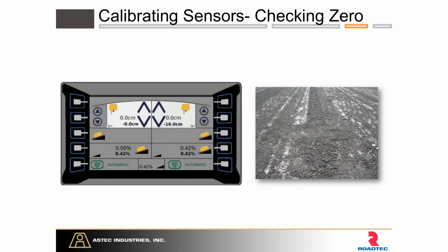So at the beginning of the day, we lower the machine down until the teeth barely scratch the surface. And at that point, we zero the machine. Zero being a verb to signify that we have told all the sensors where zero is. Now that we've told the machine where zero is, the machine doesn't know anything else other than where zero is and where it is at that moment.